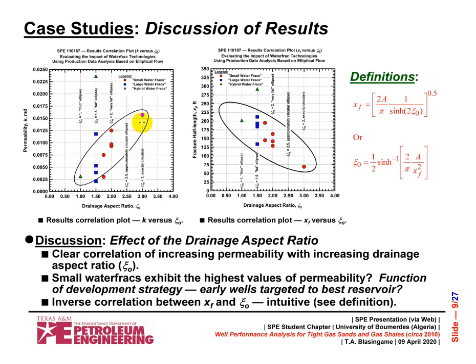So what this is really saying is that for the lower permeability cases, the drainage aspect ratio is very small, which is what we would expect. We'd expect most of the pressure drop to be coming from near the fracture and not much out in the reservoir.